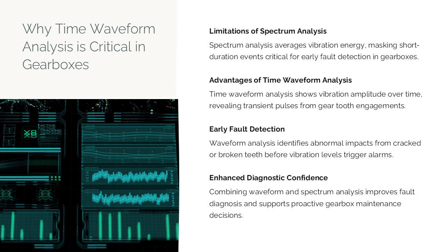they occur during operation. In gearbox applications, each tooth engagement produces a distinct pulse in the time waveform, and defects such as cracked, broken, or spalled teeth modify these pulses in characteristic ways. By observing the waveform, engineers can see exactly when abnormal impacts occur relative to shaft rotation, providing direct insight into fault location and severity. This approach is particularly valuable during the early stages of damage, when overall vibration levels may still be low and alarms based on RMS or spectral amplitudes may not yet be triggered.